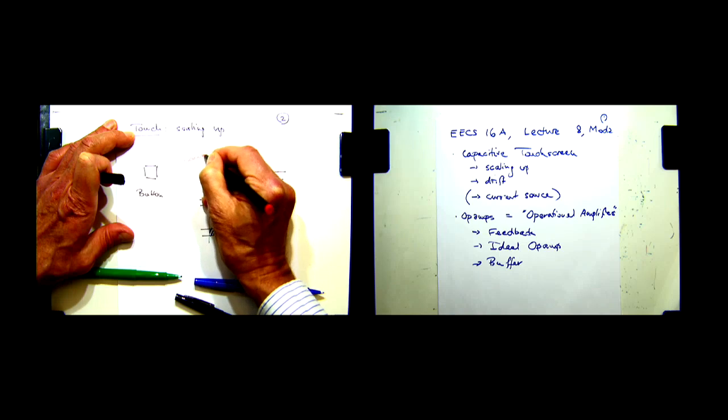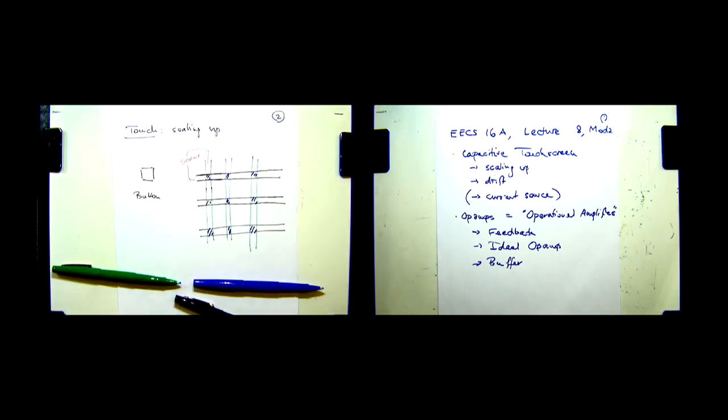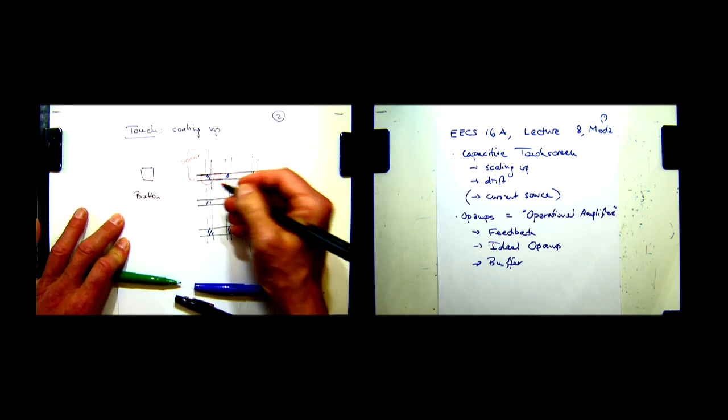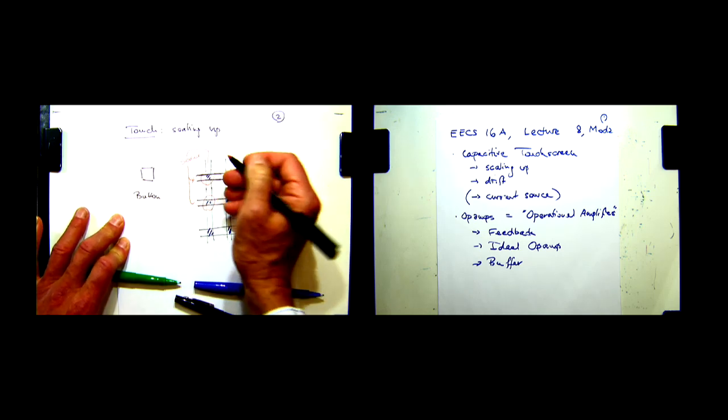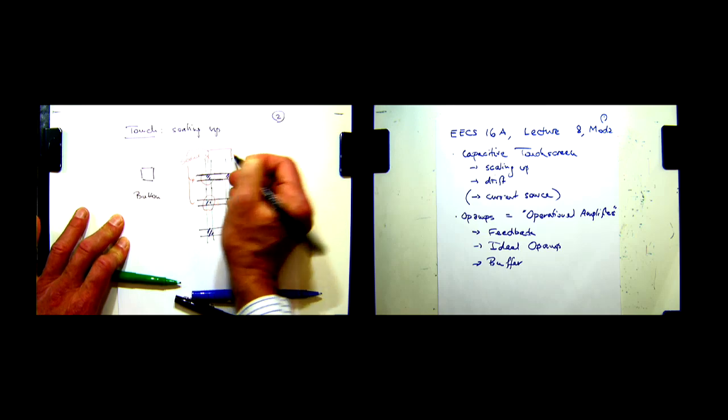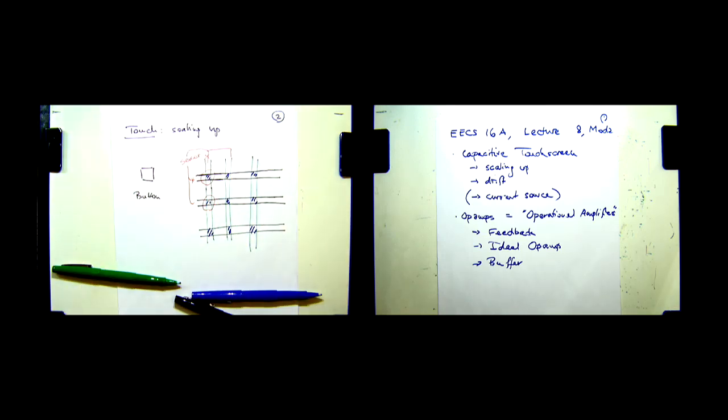Right? Okay, so how would you read this? Well, you leave it like this, and then you're going to connect a sensor between any two nodes. So let me just say sensor, capacitance sensor between any two nodes, basically the sensor with this current source and so on, and the comparator that we designed. You connect it there, okay? And then, of course, you detect touch here. Then afterwards, you remove this connection here and you put it here. Well, you would detect this one. And then when you want to detect the other column, you connect over there, right? So you can cycle through the entire array, and one by one you read out every capacitor.